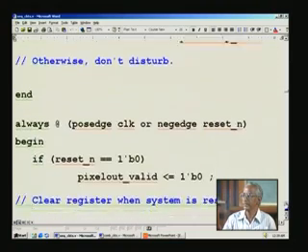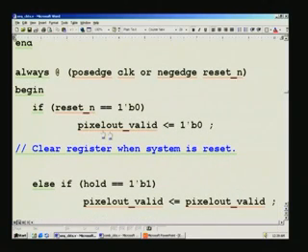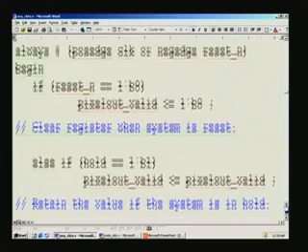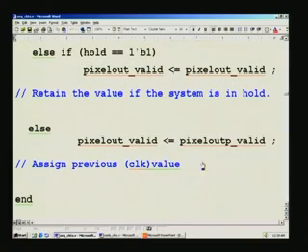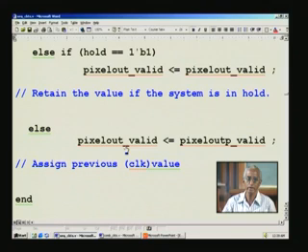And the next register takes this as the input, and precisely reset etc. are same, hold etc. are same in this next register. Here that previous content is assigned here. So that means say in the earlier clock this might have matured, it was 1, let us say, that 1 cannot be assigned right at the same clock here, and so what we do is we assign it only at the next clock. That's how we get a 1 clock delay.